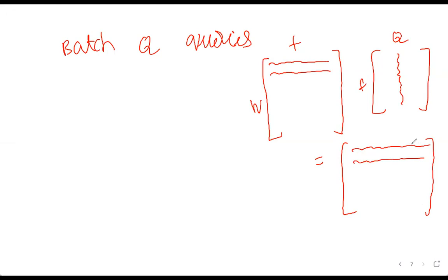Now let's say, magically speaking, you are somehow able to bring this whole query matrix and store it on the FPGA, in the BRAM memory of the FPGA, rather than streaming it in. If you are able to do that, then your operational intensity changes.